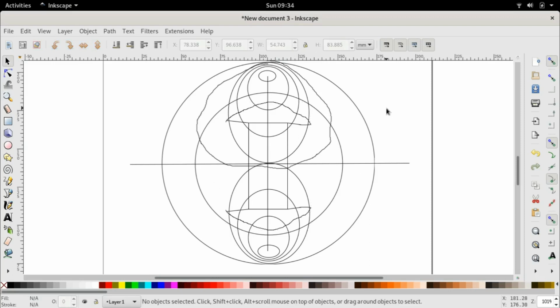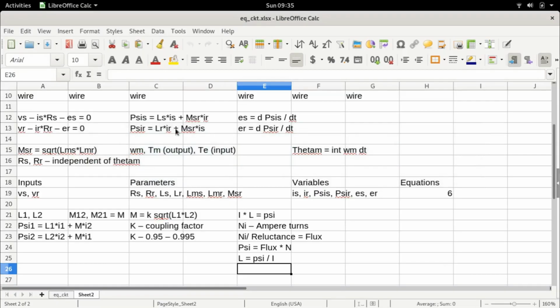So with this, I'm going to end this lecture. This is just a kind of looking at this problem from another angle. We saw in one case that there is no difference in the reluctance of the flux path with respect to the rotor position, and in this case we are seeing that there is a difference. So with this, we will get back in the next lecture to start examining what will happen to the rotor inductance and also the mutual inductance.